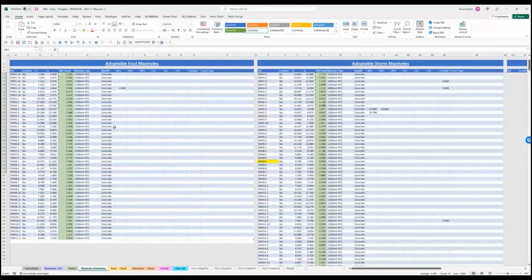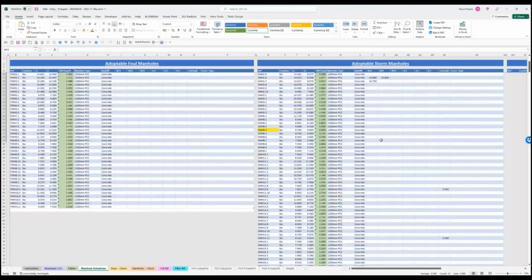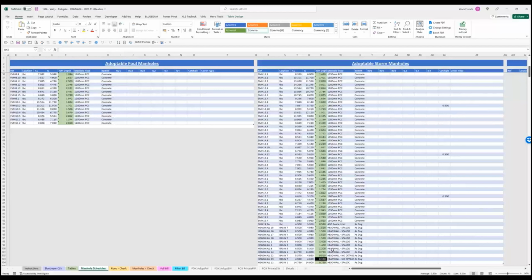We've then got a manhole schedule. Hopefully the engineers provided us with a manhole schedule. We can put our locations in here. We can put road numbers in just to break this down further, but I haven't done that yet. Cover level, invert level, manhole type, what the backfill is, and whether we've got any backdrops, what the levels are for those. Over on the storm, we've even got catch pit details, depth of the catch pit. Down here, we've got all our head walls, head wall types.